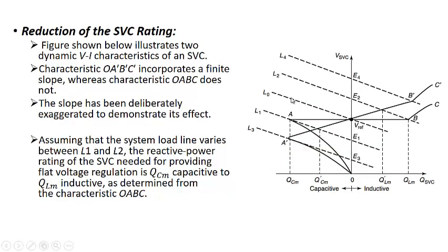Now this is the same characteristic that we have drawn earlier for the FC, that is the fixed capacitor, and the thyristor controlled reactor. But the only difference is that the x-axis is here reactive power. In that case, we have the SVC current, that is ISVC. The reactive power will differ only when we multiply this ISVC by VSVC. We get the reactive power of the compensator.